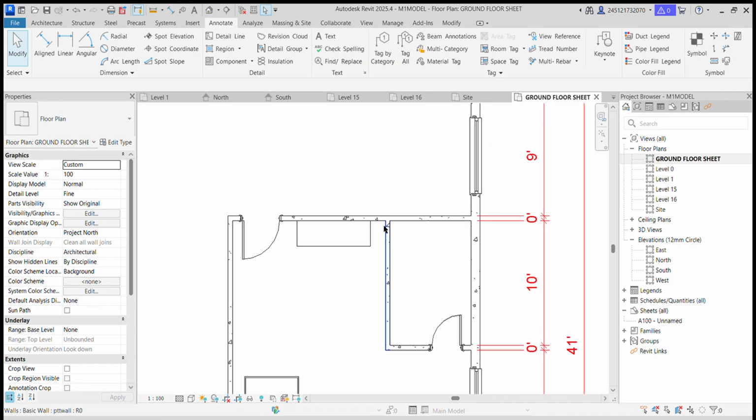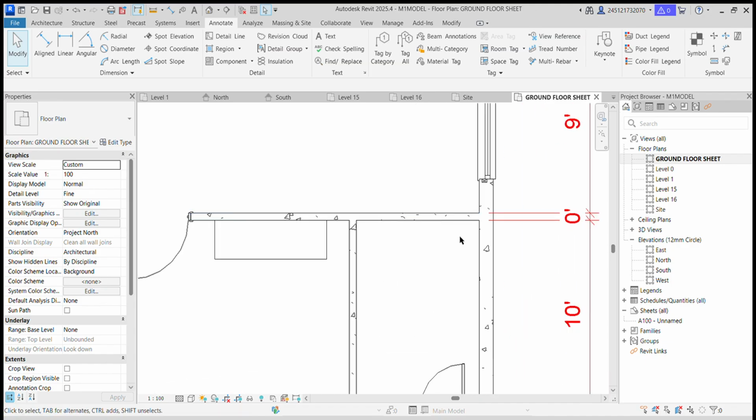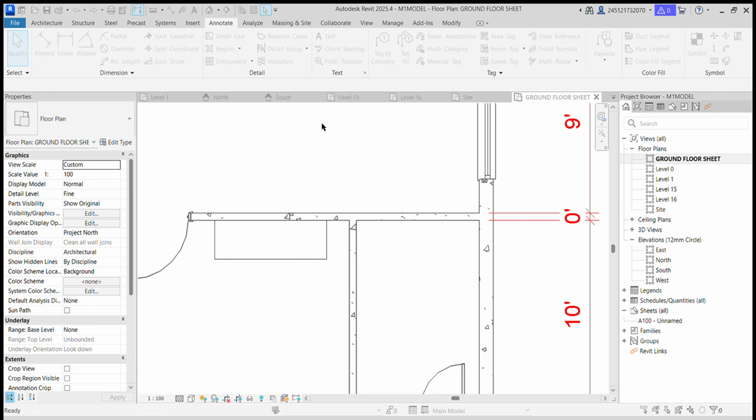I want to change the color now. The walls must show in which color? I think sky blue color. Okay. So go to the VV. Go to the walls. Where is the wall? Here, wall, right? Select the wall. We have the option here. Now I am going to cut lines. Now I change to here. Click the override, and I have to choose the color. I am going to choose the sky blue color, and it will be a solid.